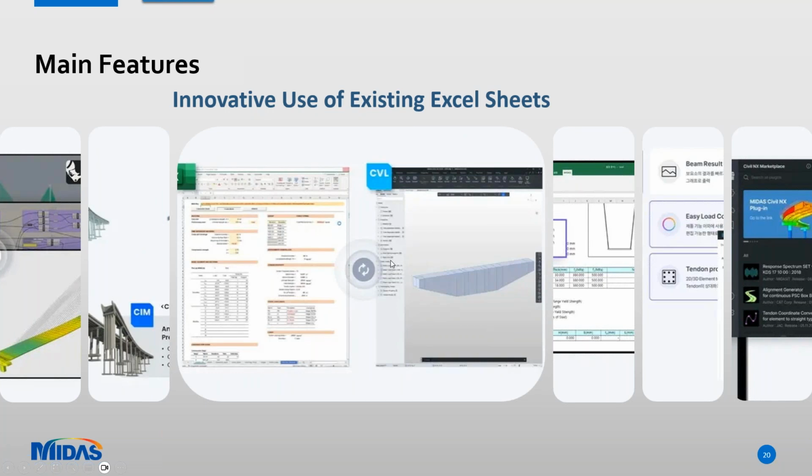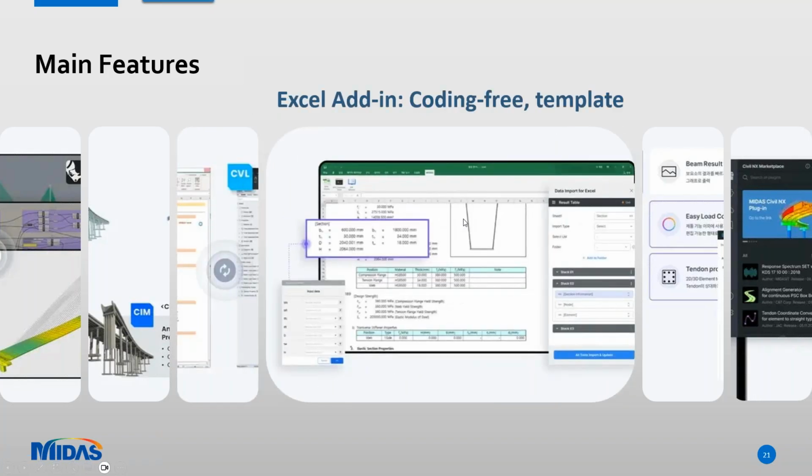So you need not rely on modeling any component either manually or through the wizards. We can generate our own customized Excel, not only for the geometry part but also through to the analysis part. So the customized Excel can be generated here through VBA.